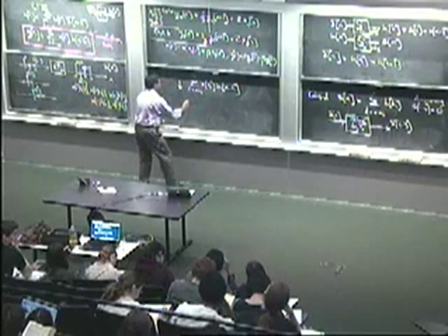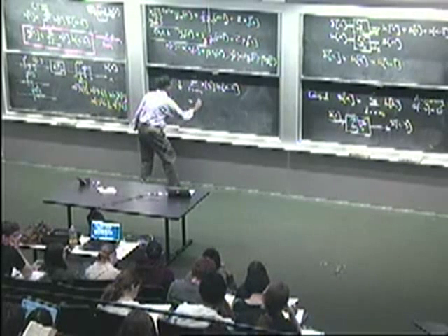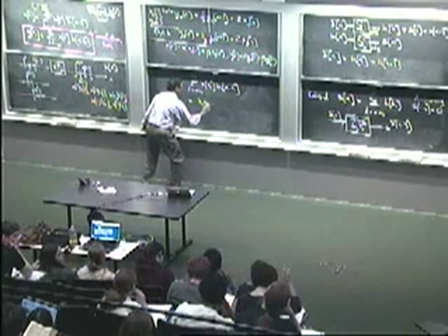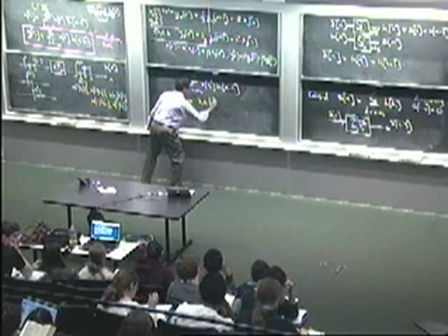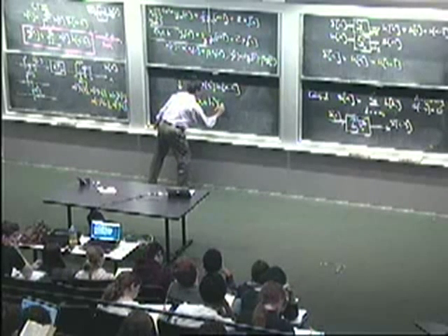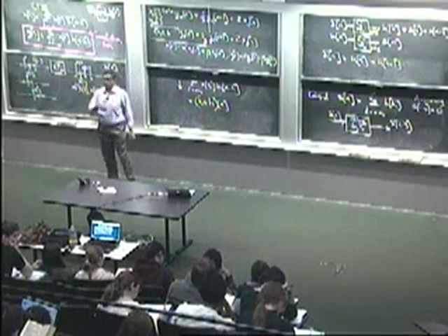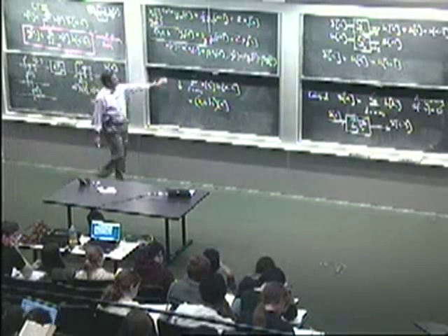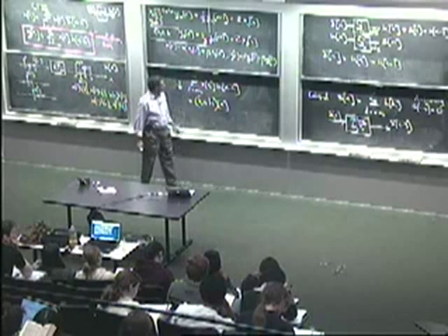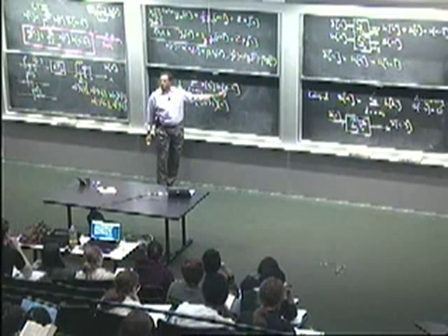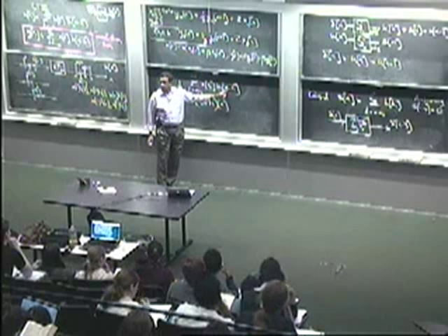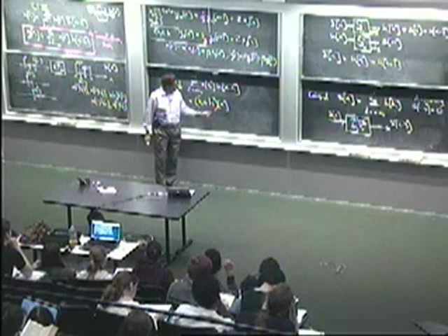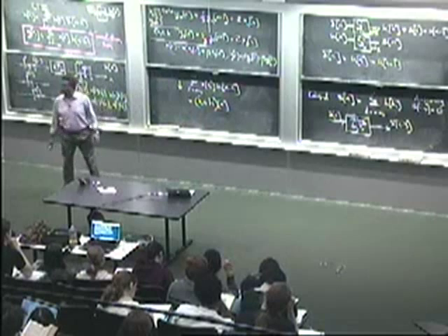And we don't want to keep writing these sums. So here's the notation that we use. We say that x is convolved with h, and we are interested in the value at time n. So this summation here is referred to as a convolution, as I said. I'm telling you what value of time I'm interested in the response at. That's the n. So that's what this notation is.